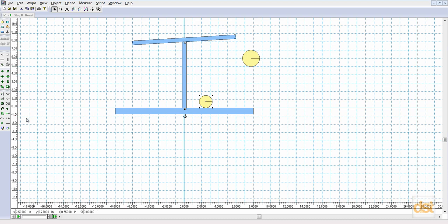And then we can click on the rope tool down here, and then click on the end of the beam. Notice how the snap point wakes up at the end center of the beam. I'll click once, and I'm not holding the mouse button down. I just released the mouse, and I can drag this around, and then notice it'll wake up the next snap point on the center of our payload, and then click, and there's our rope. So these are constrained the way we're interested in constraining them.